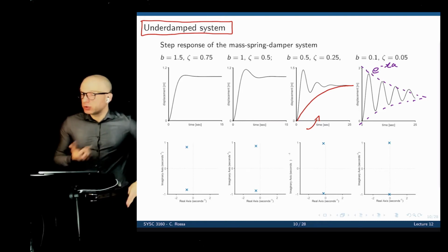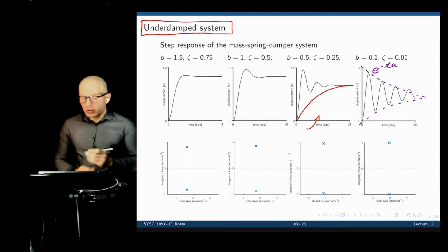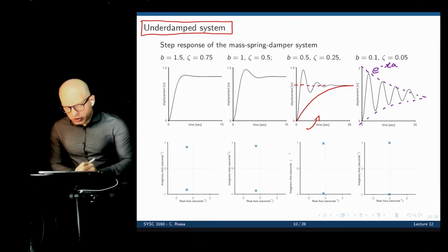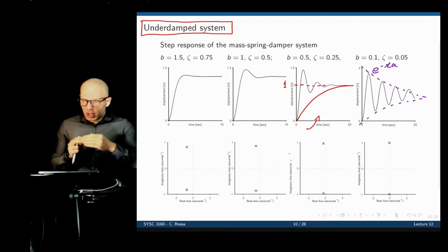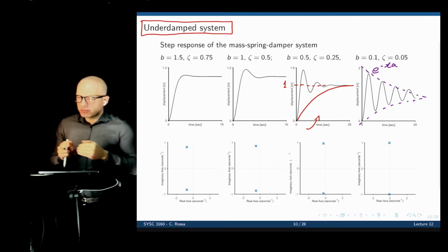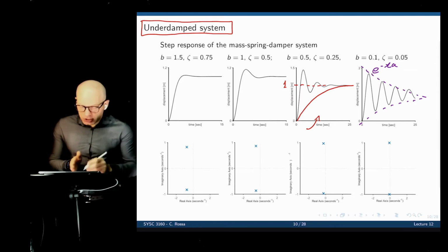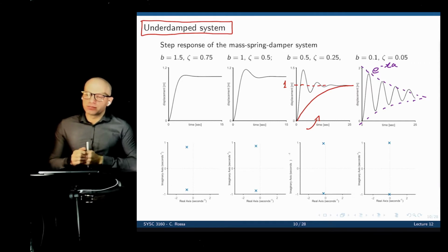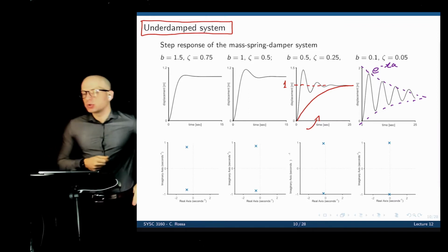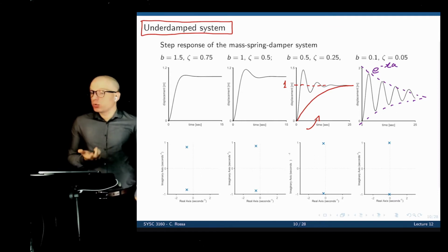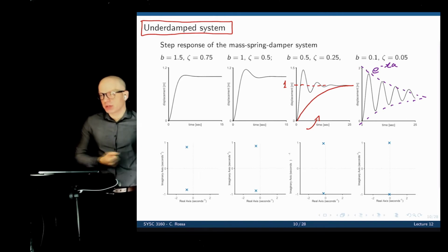There are examples where we don't want oscillations. Let's say there's a position control of a robotic arm that operates on the eye, for example. We want to reach, say, this position here, 1. We want to move it by 1 millimeter. If the system reacts too fast, it will overshoot and go to 1.5 millimeters before it settles at 1 millimeter. So you may end up puncturing the eye, right? Whereas the exponential never exceeds 1. Okay, I got it. Thank you. But it's slower. So it really depends on the application. If you want to control the drug content in the body, for example, you don't want to overshoot. You don't want to overdose. So it would also be preferable to have a slower, overdamped system.